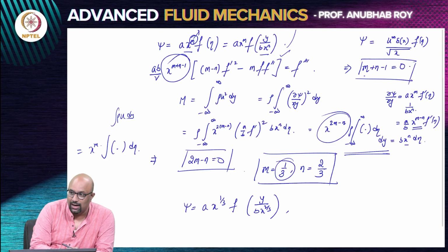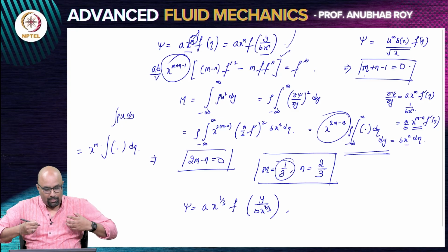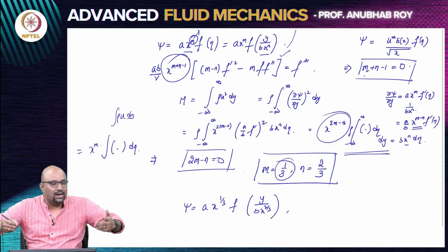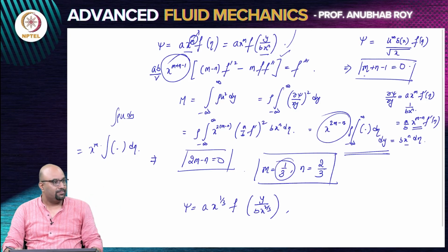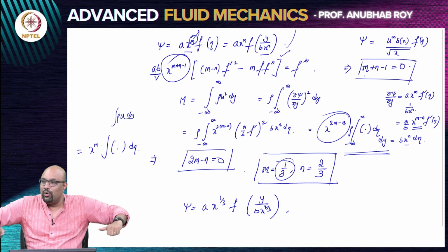Right? So that particular integral, the mass flux that I am calculating at the next location, because you are pushing in fluid, you are bringing in fluid from the side, so automatically you have to carry more fluid out. If I am pushing in fluid from the inlet, that is the jet bringing in fluid. The jet is entraining fluid from the side, from its lateral boundaries, it is drawing in fluid.